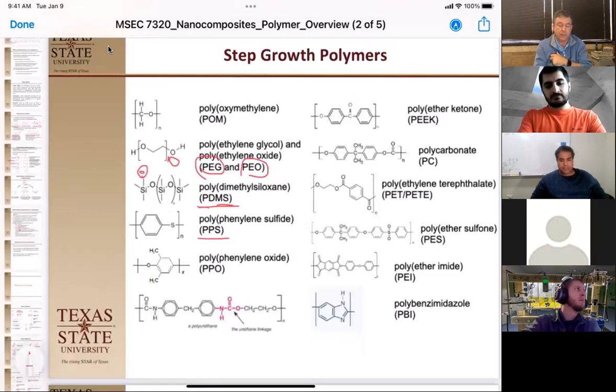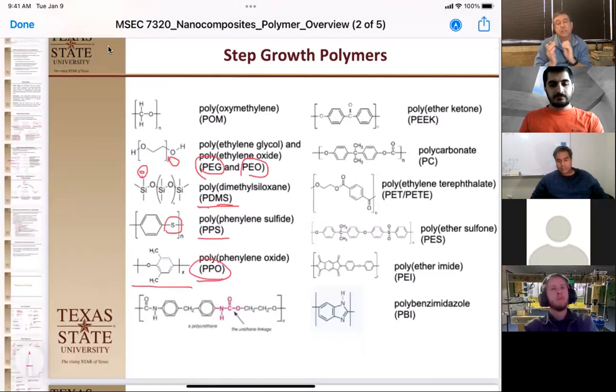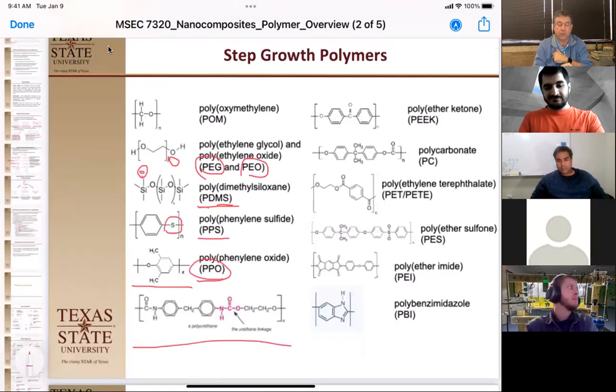This one right here is used a lot in electronics for packaging. It's polyphenylene sulfide. So it's like a benzene, it's like an ether, phenylene ether, like this one here. This is again used in a lot of packaging because it's not very soluble, but it's melt processable. Okay, and then this is, the general term is polyurethane because of this urethane linkage here in the middle. It can be made a number of different ways, both as fibers, plastics, foams, films. That can be made in a number of different processes, but it's this urethane linkage here that names it.